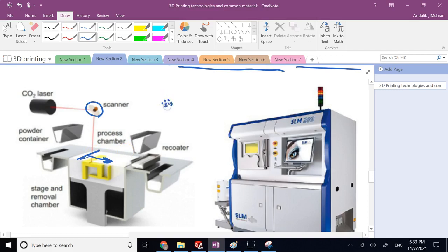So you have all of this powder right on the bed, and then the laser is going to target a specific area. Let's say the laser says, hey, I want this area, I want to focus on that. It shines the laser and makes all of this powder do what? Get fused together, get molten or sintered together, and makes that solid part. And then again, this arm comes and grabs one more layer of powder, and it is built layer by layer on top of each other. That's what we call the recoater.